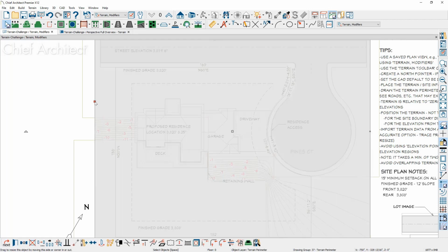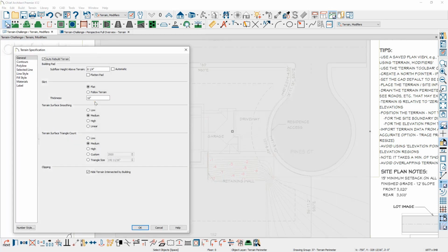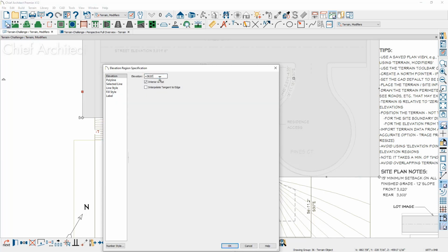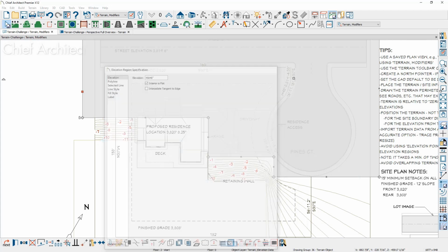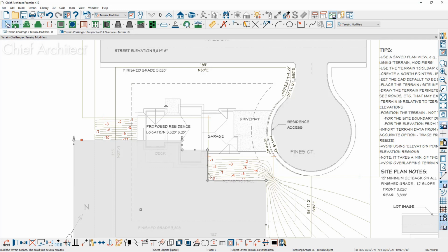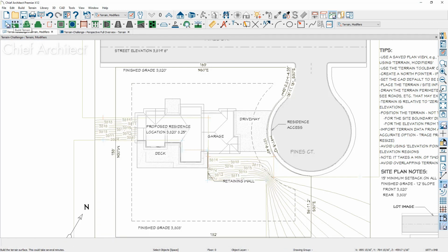Here's what I'm going to do. I'm going to open up the terrain perimeter and I'm going to come into where our subfloor height is. And I'm going to say plus 3820 in feet. Let's just go ahead and copy that number because I'm going to have to use this 2 more times. Plus 3820 feet. And then I'm going to do the exact same operation on the terrain regions we created, plus 3820. That will resolve in inches. And then we'll just do the same thing. Plus 3820, rebuild the terrain, and now you can see those are now displaying in sea level numbers.